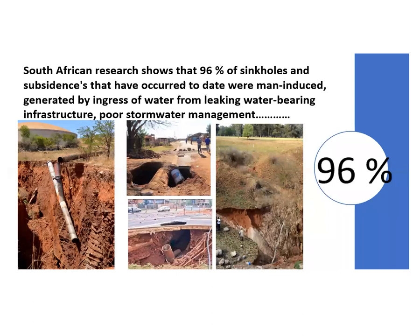One's in the middle. I think the one at the bottom middle is in Pretoria somewhere, where the sinkhole was the size of, could swallow a car. And it's just as a result of poor infrastructure. The joints not properly sealed, water started to erode, the erosion caused some areas of dolomite to dissolve, and then it just starts caving in and it causes a huge risk.